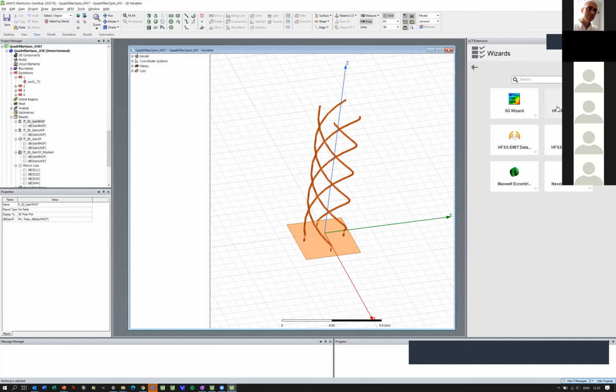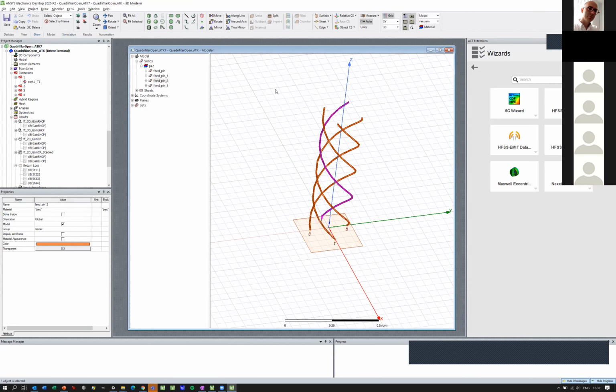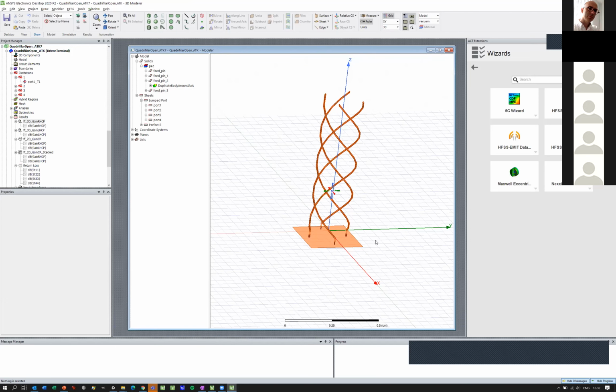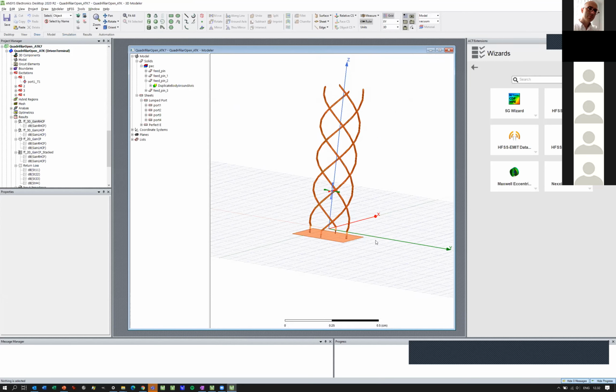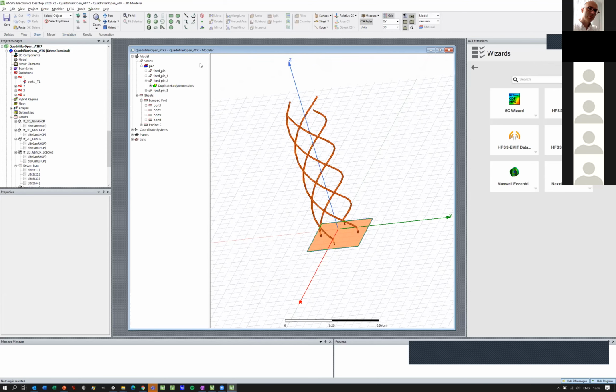But basically, these with charts are easy, and you can always go and edit that after that, or you can copy paste. Just select everything, Control-C, copy, and you can copy that to your own design and play with that. So it's an efficient way to build up your own antennas. Not only antennas, but there's also Maxwell, and you can download this with charts from the Ansys webpage. There's more. I'm just playing with the higher frequency, so we have just these few visible here.